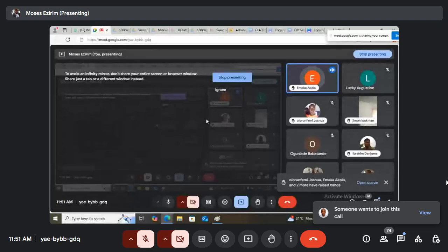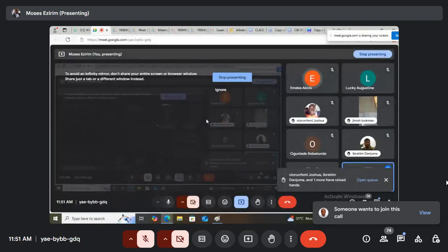Second question, sir. If you install that large capacity, like you said, you have a 4 megawatt capacity of PV, what is the overall generation from your experience, the maximum you have ever seen if you install 4 megawatts? Okay, of course, for the 4 megawatt, I'm seeing 2.5, I'm seeing 2.6, 2.7. The maximum I've seen from it is 2.8.